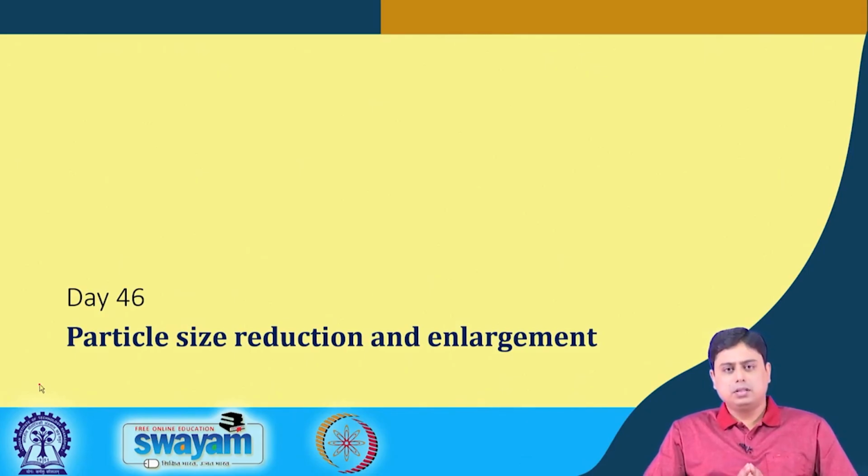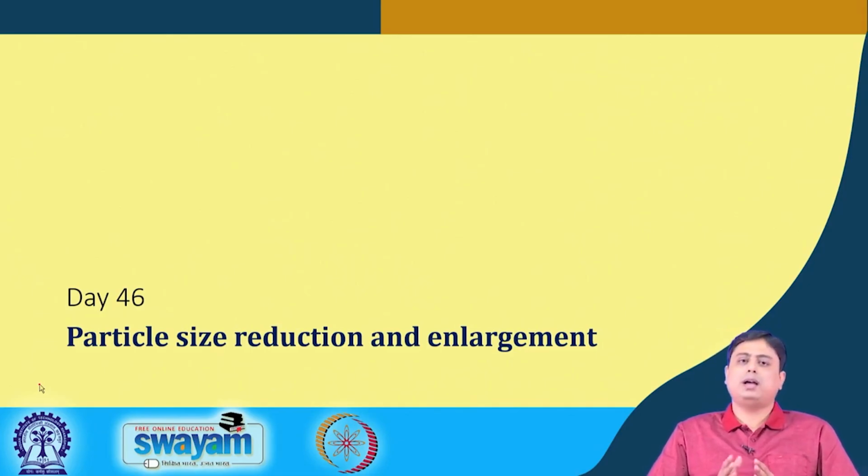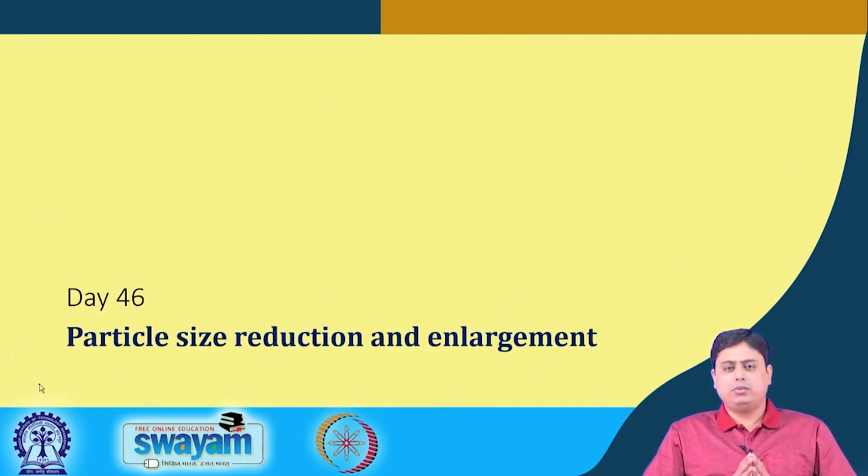With a couple of examples, we have seen the utility of these laws, how they help in estimating a primary guess value of the energy requirement. Although this is not the actual requirement for any equipment, which is much higher than that, it gives an idea of the order of magnitude of energy required to go from a certain size to a smaller size range, and which law would be more appropriate and why, we have discussed this as well.